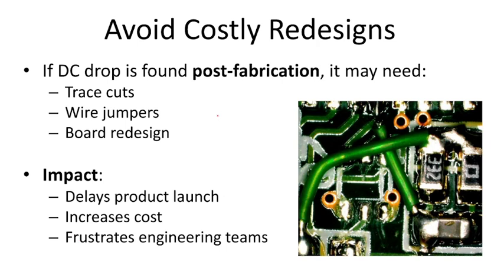As I mentioned earlier, it's a very common practice that people ignore this analysis in the development stage. They just take this design to manufacturing. Once that PCB is fabricated and they are doing board bring-up activities, they see the DC drop or voltage drop issues, and the IC is not functioning well because we have a huge drop in the path. At that time, they come up with a lot of problems, like they do some stuff on the PCB which is not very easy and very time consuming, and sometimes it also causes other sections of the design to fail.